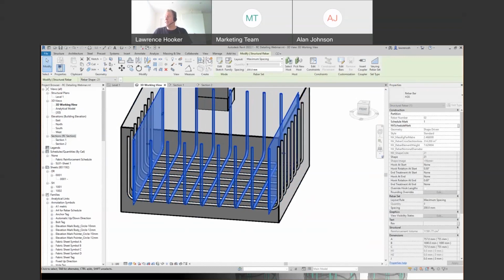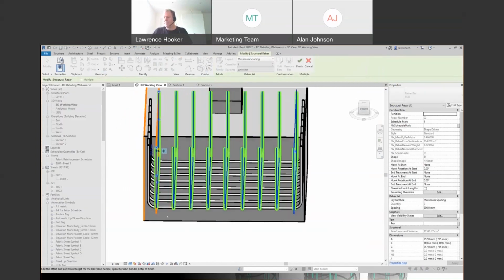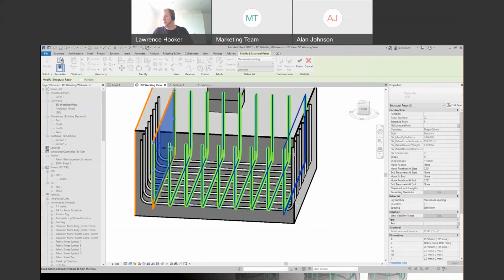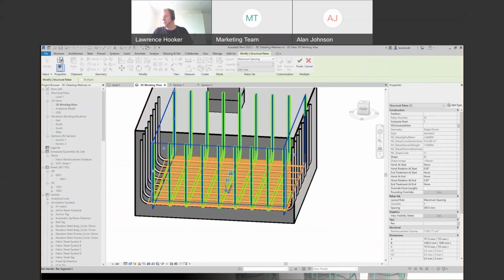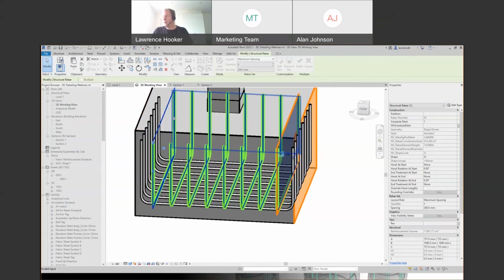And now, even in 3D, we can use edit constraints. So you can see over here, we're currently going from the edge of the concrete, but I'm going to go from the edge of the cover again in here. And again, I can then just say -150. So that's got exactly the same layout as my previous layer in here. And then we can go and pick on the next face over here, the next leg of the reinforcement bar, which is this one here. Again, we've just got to make sure that it's going from the cover in this example, and then -150. Okay, so that layout is now complete.